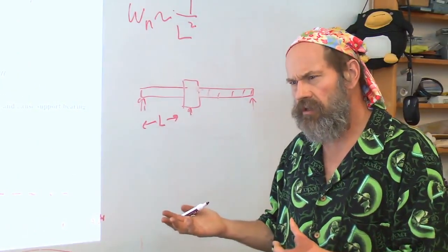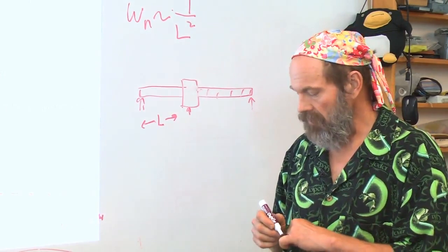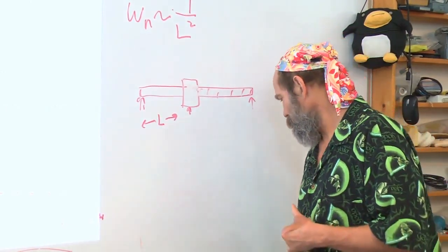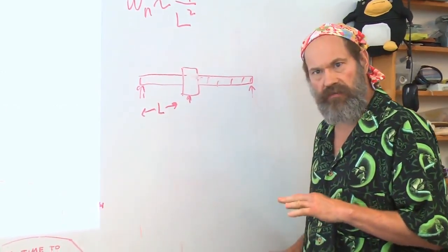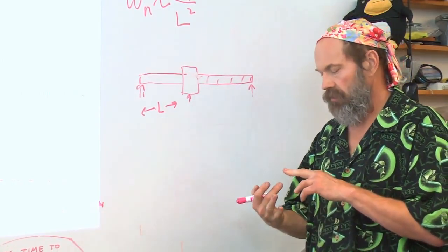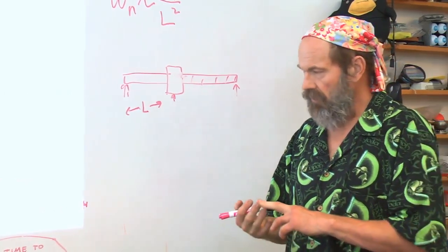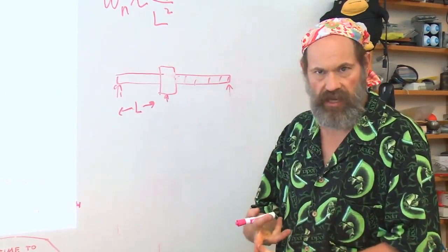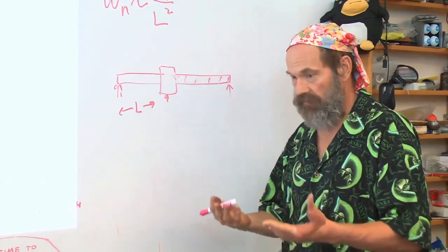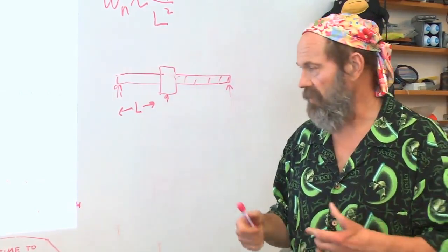How did the motor torque go with the diameter of the shaft? To the 4th power. So this is where system design comes in very importantly. See, we've gone through the stiffness of the shaft. This motor torque is a function of diameter also, and we worried about the stresses in the shaft. And now we're worried about the shaft dynamically shaking, also affected by the diameter in a big way.